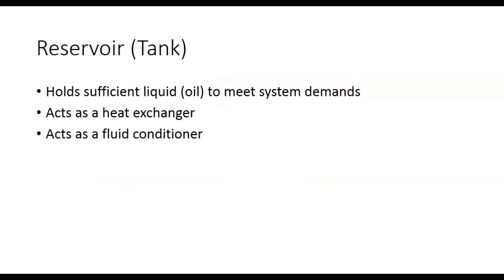The reservoir, or the tank, just about everybody calls this a tank. In hydraulics, we have to have a tank. We bring the fluid back and put it into the tank. Usually when it comes through, it'll run through a strainer or something. And then when we pump it, we'll pump it off the bottom of the tank. Heat exchangers, yes. Anytime we move things, it creates heat. I don't know if anybody's been around hydraulics, but everything's moving, and you'll notice the tubing is warm, right? Because we're moving things under pressure. It acts like a fluid conditioner.